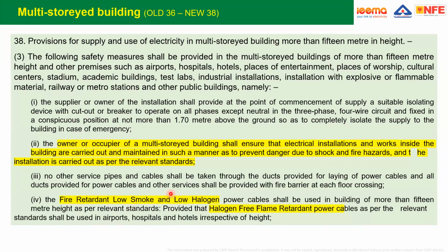Okay, okay. Because I could also gauge similar contradiction in the CR value, where CEA mentions the CR values of class 5 conductor, whereas the NEC talks about the conductor resistance values in wires of class 2 conductors for all the high-rise buildings, for all the fixed wiring. So that is also a contradiction. So in all such cases, CEA shall be valid, right?